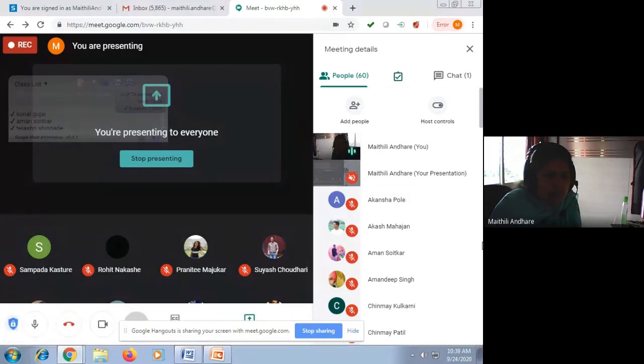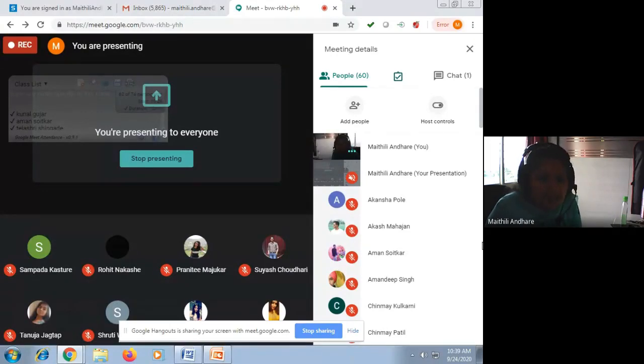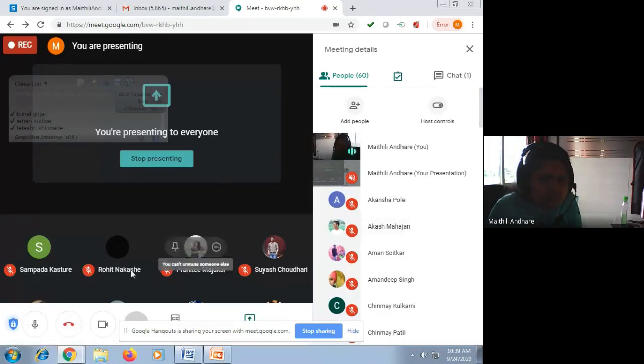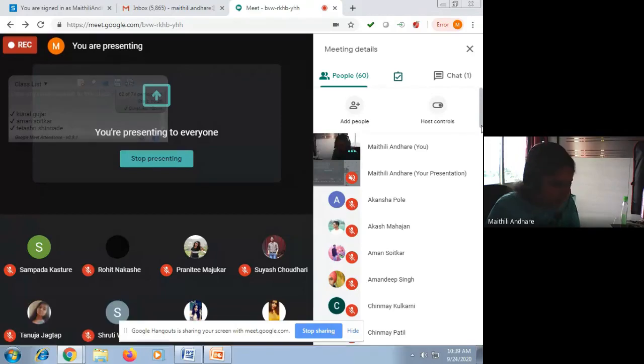According to your understanding, make it on and off. Then start the timer, poll the timer overflow flag, clear the timer overflow flag, clear the timer. That's it. So try to write the code. I will give just 2 minutes. Everyone should write the code on their own. I will ask randomly any one of the students.